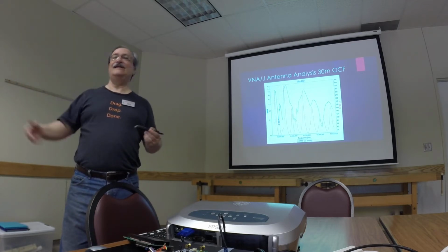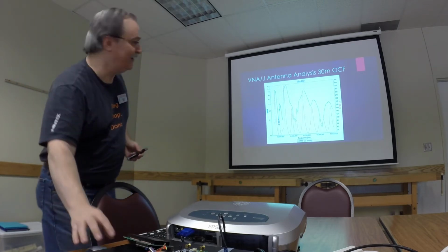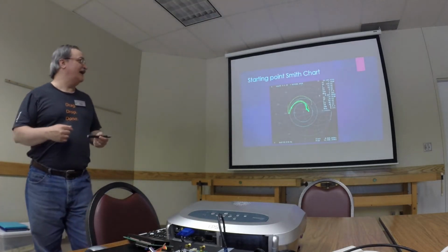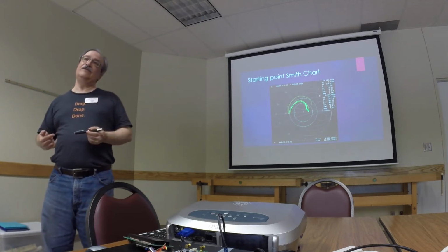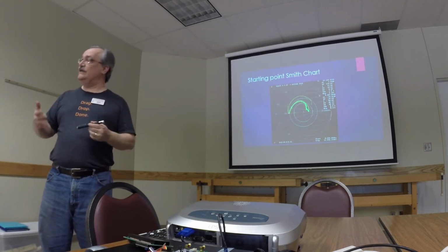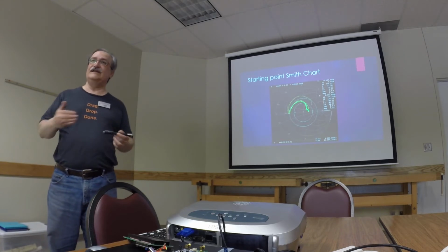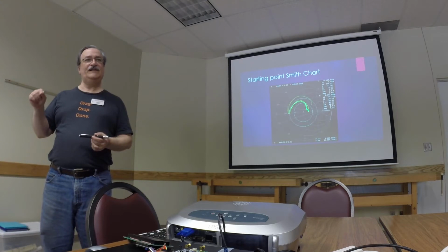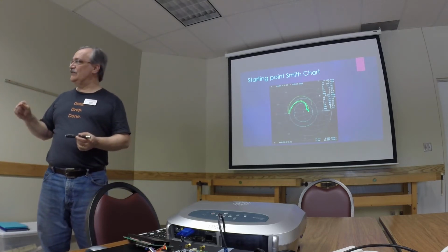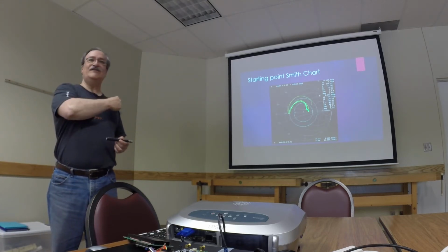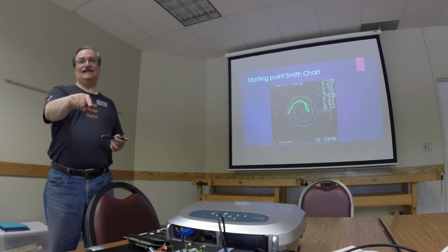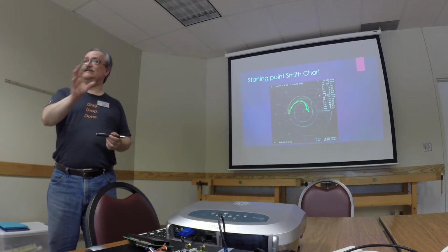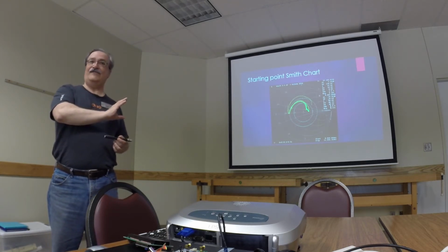Right? Well, the VNA helped me with that to understand what kind of parameters I was dealing with. But any good antenna analyzer would do the same thing. However, interestingly enough, the MFJ-259C that I've been relying on for several years didn't tell me this at all. This thing did. It was spot on the impedance, whereas the MFJ unit was way off.